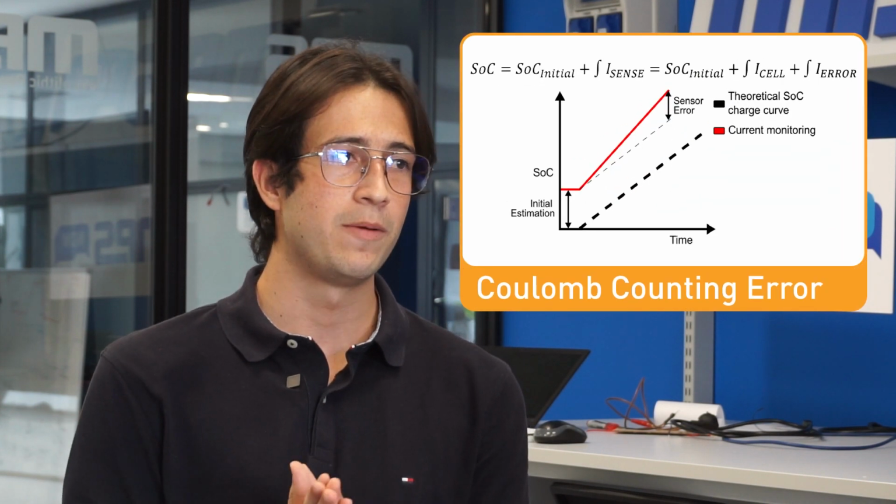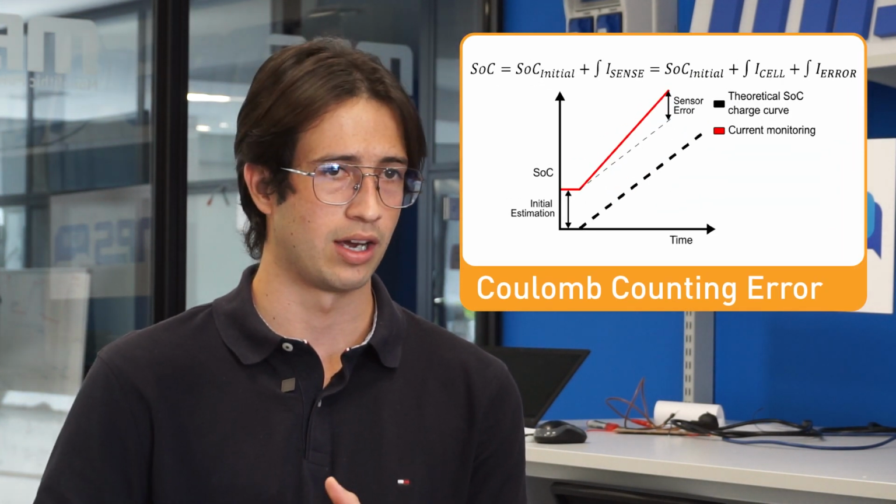Okay. And then what if you have a way of recalibrating? It sounded like there are still errors in between as the battery discharges. Can you talk in more detail about why there are errors? Yeah, because if you are integrating the current, the measurement of the current from your battery monitor is going to have a certain error which is inherent. You are going to have it. Since you are integrating, you are deviating from the real state of charge line.